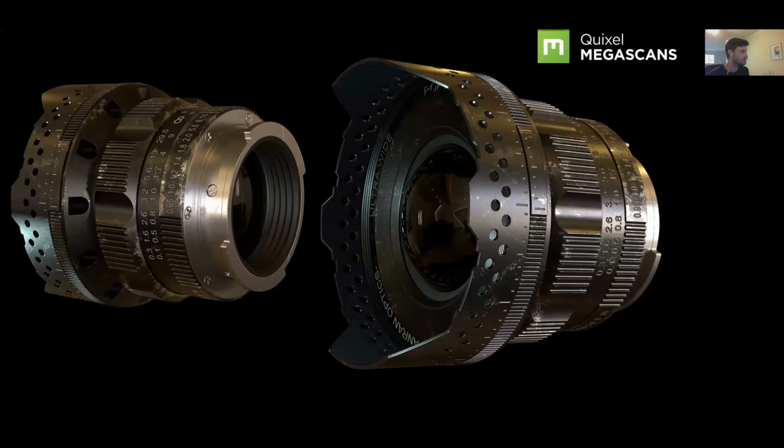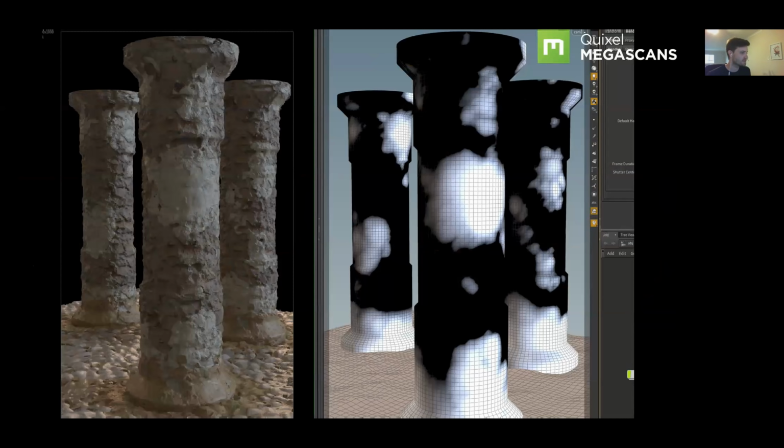Another great example with sort of powder coat with sort of metallic chrome underneath. And it's also incredibly useful for environment artists, right? For instance, you could have 20 columns all next to one another, and you want to make sure that they don't all share the same texture. What you can do is use a triplanar workflow, so you have axis-aligned texturing and 3D-aligned noise to drive your procedural blending. In this way, each of these pillars look more or less entirely unique, which is very useful.